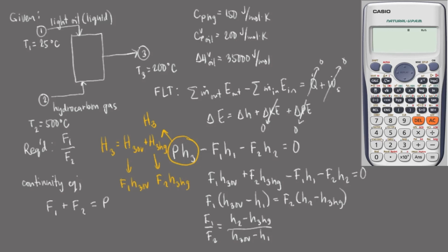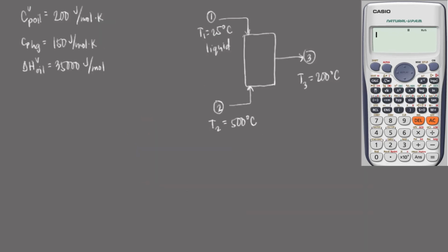Of course, we could always use the equation enthalpy is equal to Cp times delta T. However, these enthalpy terms are absolute enthalpy terms. Therefore, we can only get their values if we establish a value of the reference temperature. Let us first establish our formula for the determination of the enthalpies. In general, we determine an enthalpy as Cp multiplied by the temperature minus a reference temperature. Remember that all enthalpy values are always against a reference temperature. And we can also set our reference temperature here as long as for all of the instances, we will only be using one reference temperature.